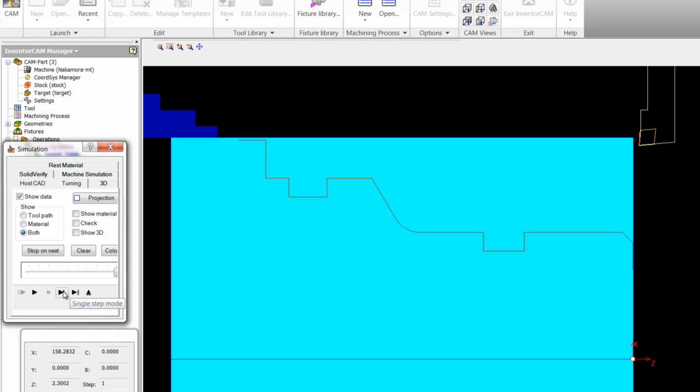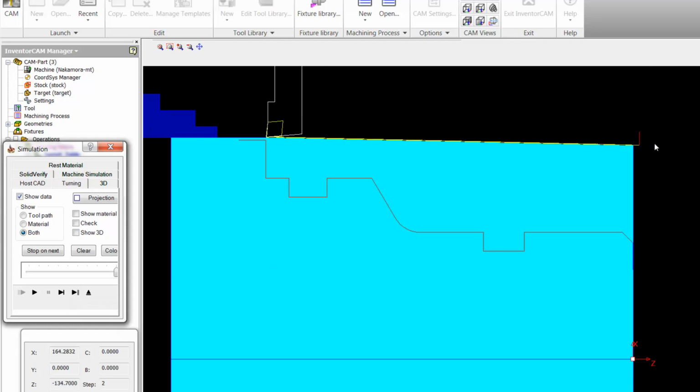Now, as it goes across the part, you'll note that it ramped its way up. This is the ramping option actually happening over here, and the advantage of this is that when it starts cutting, it starts on the full surface as shown over here, then gradually works its way down. Thereby, what actually happened is the chip load changes on the edge, allowing for less wear and tear on the